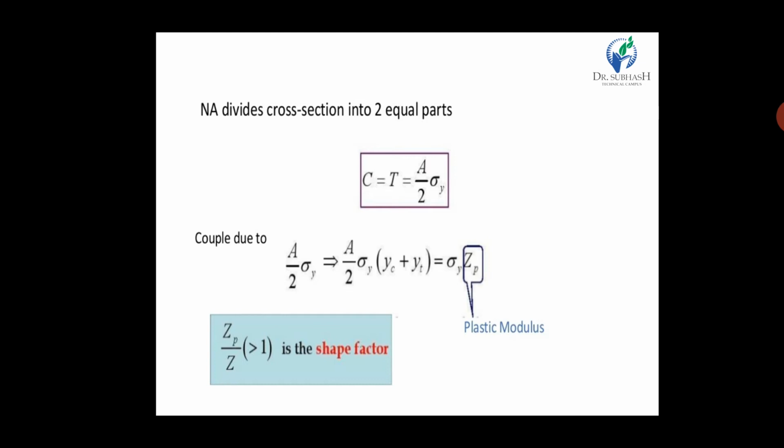Now, a few of the disadvantages are: there is little saving in column design, so that's why we are not introducing it in columns. We introduce it only for beams and portal frames. Second disadvantage, it is difficult to design for fatigue and the structure is complicated. It is difficult to obtain the collapse load.